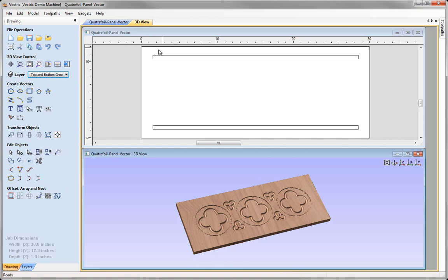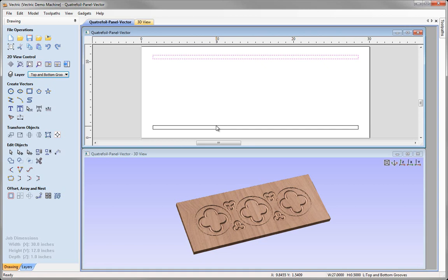What I want to do here is cut each of these grooves with my ball nose tool to run this scalloped shape along the top and the bottom. And I've drawn these actually at the width of the groove that I want to cut them. But really what it makes sense to do is for me just to run the tool down a single line here in order to create the effect that I'm looking for. So I'm actually going to sketch a couple of vectors just snapping to the midpoint of each end of these lines.